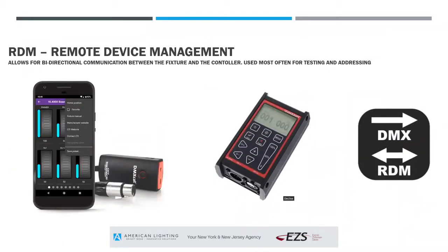RDM, remote device management, that again is for the bidirectional communication between the fixture and your controller, or potentially through just an RDM device. Generally, we see it used for testing and addressing, although like I said, we are seeing more applications where RDM can then communicate back to a control system, things like how long the fixture's been running and operating temperatures. So if you have a fixture that's running a little hot, that might cause an alert where you want to go check it out and see if it needs to be repaired or replaced. It also can show you runtime, so you could anticipate end of life potentially.